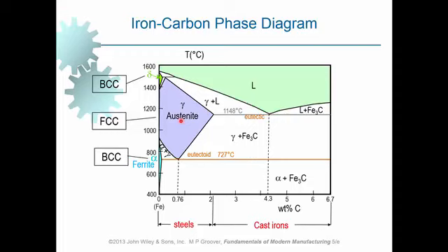So the atoms of carbon cannot move out of the crystal structure, and they are trapped where they are. And because of this, there will be a large content of carbon in the steel, and you can make them really hard. You've noticed how we make the steel hard. We put it in the furnace, right? And we quench it. So atoms of carbon diffuse inside of the crystal structure, and they are trapped wherever they are. But if this happens gradually, they may find the time to move out of the crystal structure and find right places for them to form some deposits of graphite, making it softer. So we can make use of this property in heat treatment processes.